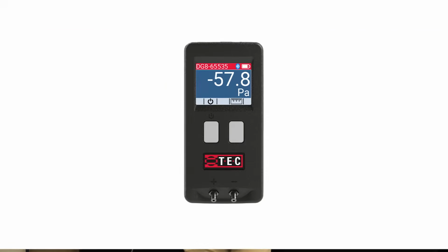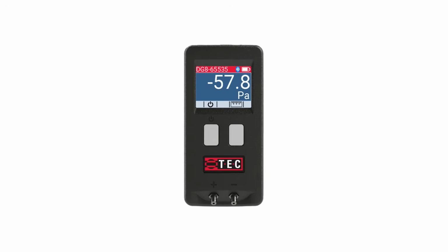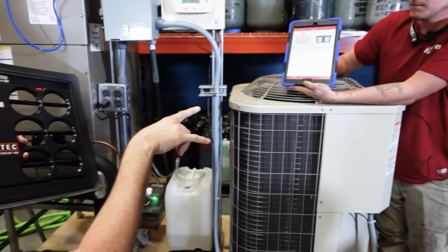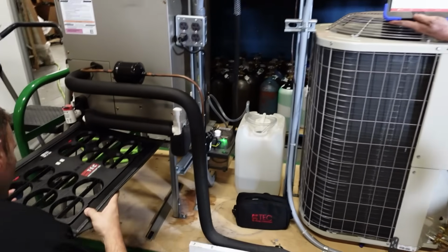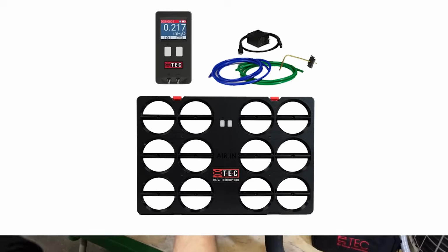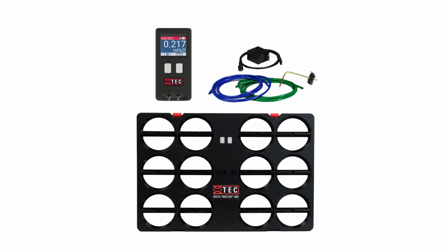In order to measure in the Pascal range, you need to have something called a precision manometer, or generally speaking, they're a blower door manometer. It's a really expensive manometer. Recently, the Energy Conservatory, TEC, came out with a much less expensive version, which is a single port version of a precision manometer called the DG8, which is pretty revolutionary. Those of you who were in the class where we talked about the TrueFlow grid, where we're measuring airflow directly in the system, that uses a DG8 manometer. And a few of you here have a TrueFlow, right?